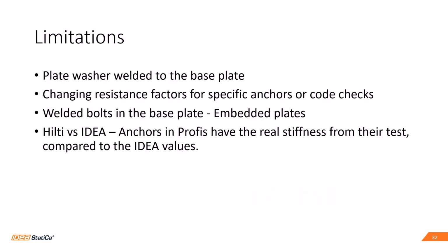With that being said, here I have some limitations, but we are working on those to have better results and to implement some things into the software. So as mentioned, plate washers welded to the base plates are not possible in the software, so you cannot account for that reduction in the shear for the anchors.